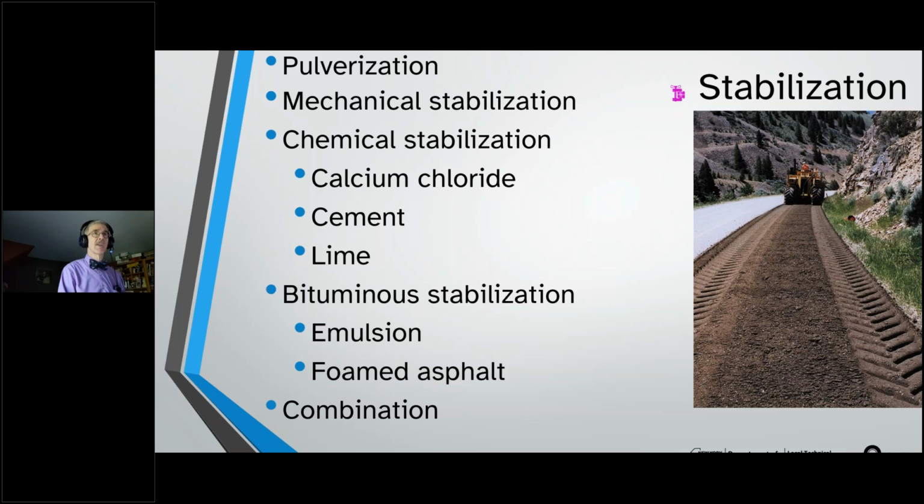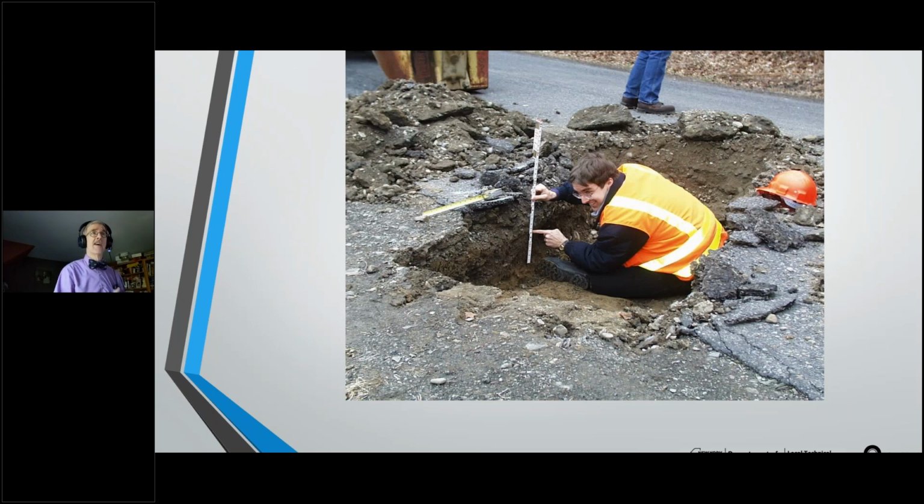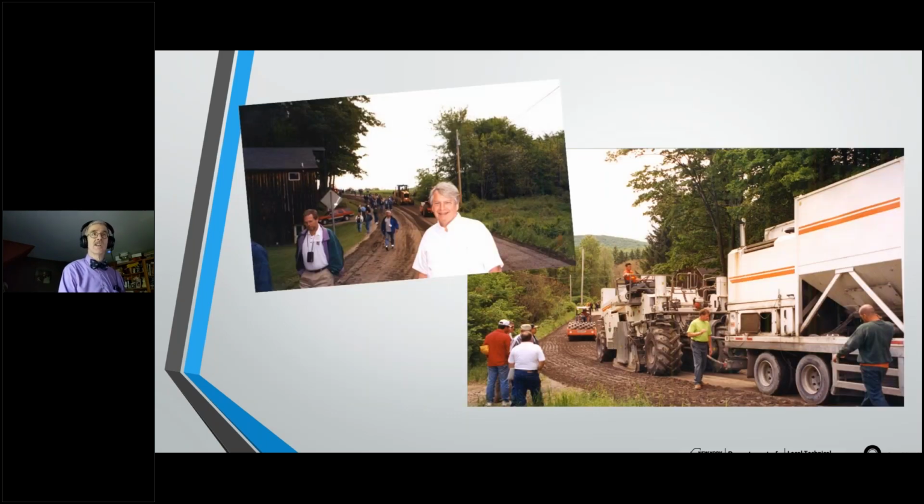Which do we choose? Well, there's only one way to really know, and that's to do a test. You have to go and do a test to see what you've actually got, and then decide on what stabilizer to use and do full depth reclamation. It works fairly well. It's fairly efficient. This is a project we did back when I had our old director, his name was Lynn Irwin, and we did a cement stabilization as part of our biggest event of the year, where we've had 500 people out on a road.